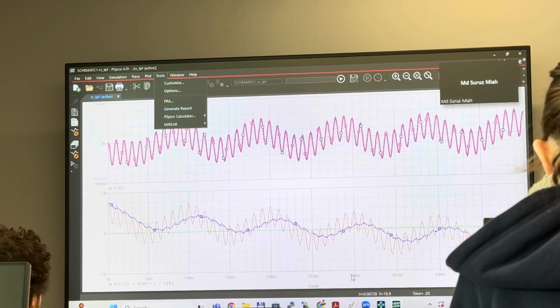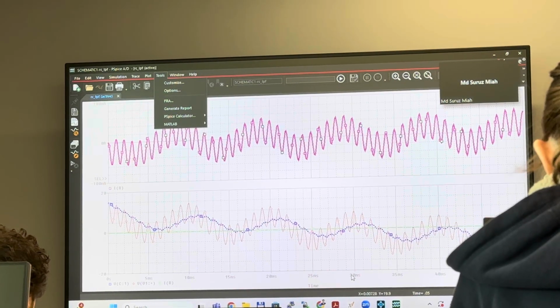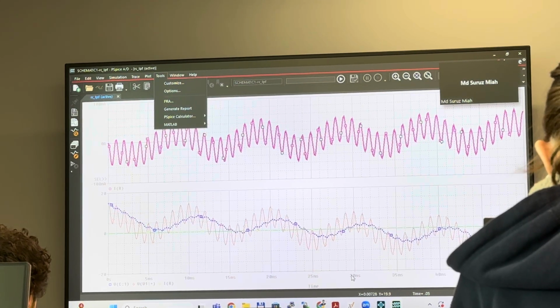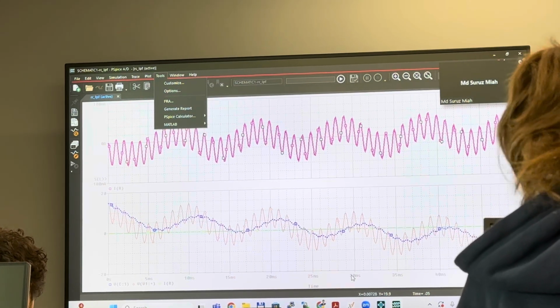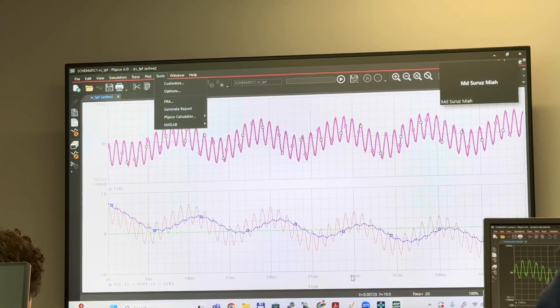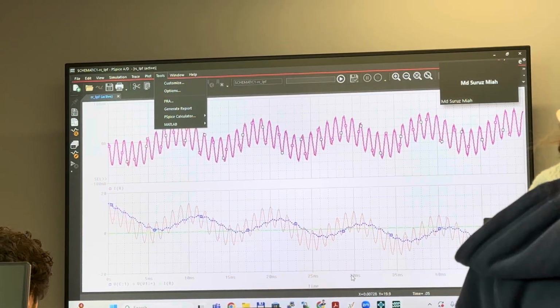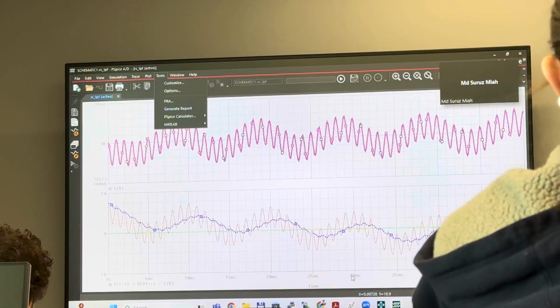So when I tried to plot I1, I got 0, even though my voltage graph was right. Yeah, 0, you plot it in a new window because the value of I is in the range of milliamps, and the voltage is in volts. Okay? So if you look at the scaling, yeah, you will see there are some values, but because of the scale factor, you don't see this physically. You plot it in a new window. There we go, okay. You got it now?